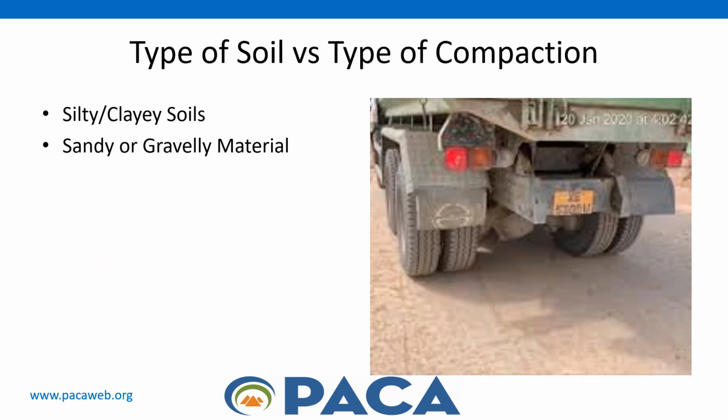If the soil consists of silty or clay materials, initial compaction should be done with a vibratory tamping roller or a pad foot roller that compacts from the bottom to the top of the subgrade. This type of roller should continue until the required minimum density of compaction is achieved, which is usually indicated by the pad foot roller walking out of the impressions it leaves in the soil.